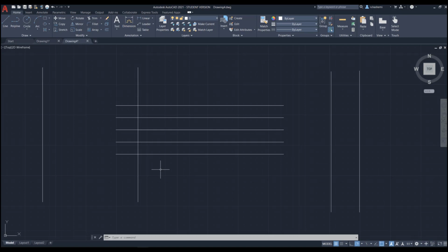Okay, so I'm going to go over the quick mode quickly. For trim, we have an icon which is located here, and the shortcut to the trim command is TR enter. So easy. As you hit TR enter, you need to pick the objects that you want to be shortened. You just need to click, and then you see this line. You just need to go over those and they will be shortened. That's easy.